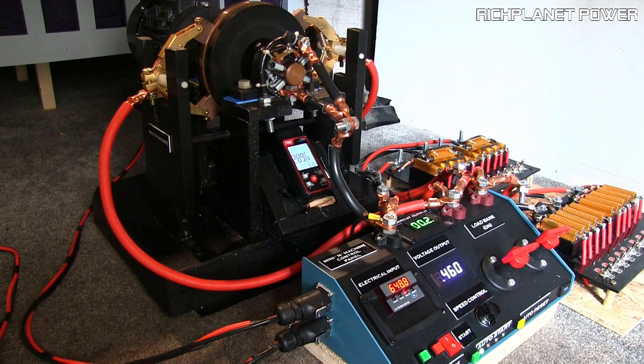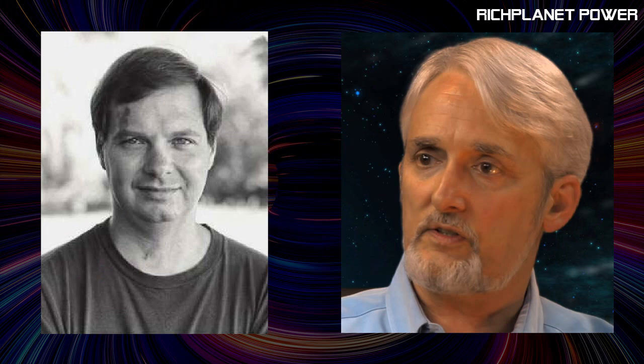Using metal liquid contact will also reduce the frictional force of the brush on the disc, thus minimizing frictional losses. In my opinion, from my results and looking at De Palma's results, it can only work by using liquid metal contacts within the machine. And this is exactly what both Trombley and De Palma were striving for in their later machines. De Palma used mercury and Trombley used sodium potassium eutectic known as NAK78.